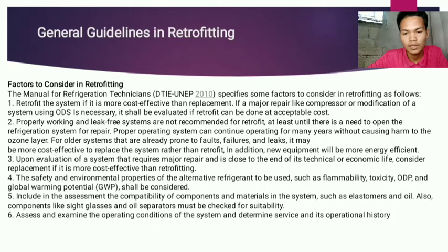Here are the factors to consider in retrofitting. First is retrofitting the system if it is more cost effective than replacement. If a major repair like compressor or modification of a system using ODS is necessary, it shall be evaluated if retrofit can be done at acceptable cost.